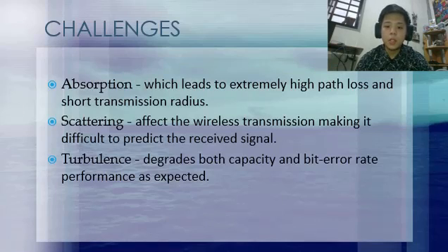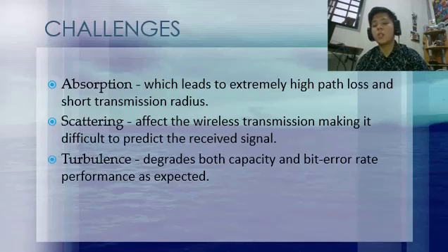And the challenges for these fundamental waves are absorption, scattering, and turbulence. Absorption leads to extremely high path loss and short transmission radius. Scattering affects the wireless transmission, making it difficult to predict the received signal. Turbulence degrades both capacity and bit error rate performance as expected.